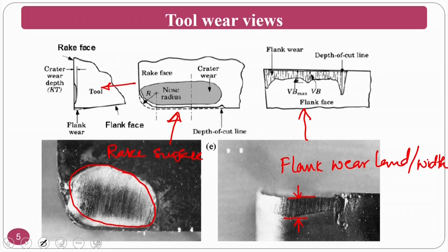One noting point you have to always see here, and I will come to a question that I will explain: the crater wear starts slightly away from the cutting edge. That is what you have to observe. I will ask you one question and I will also tell you the answer.